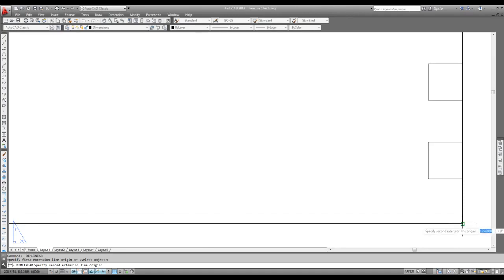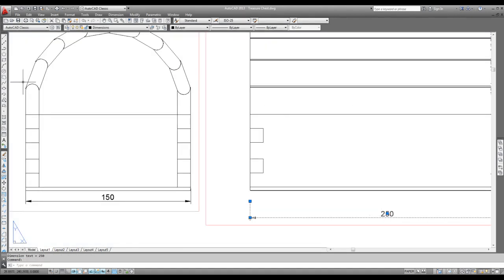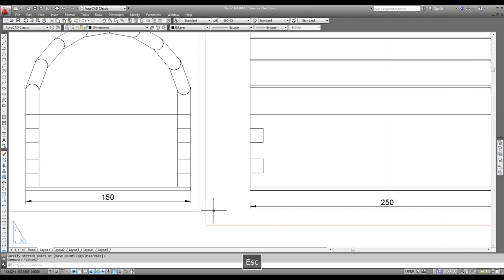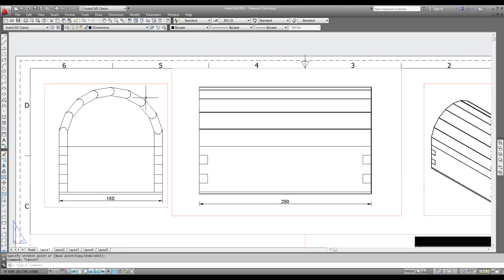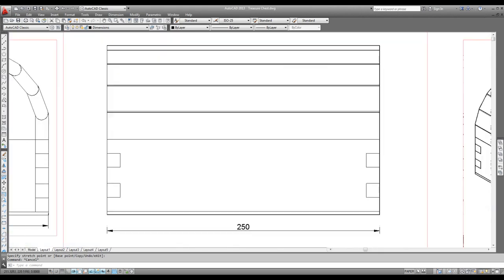So it's not a fixed dimension, whereas these two dimensions are fixed. They have to be this size. If the timber hasn't been cut properly, it won't necessarily be this size. If you haven't cut the fingers correctly, this could end up being 145. That means the lid won't fit. The base will have to be cut different to size, same as the length. If you make the body of the treasure chest smaller or bigger, the lid won't fit. All these dimensions have to be right.